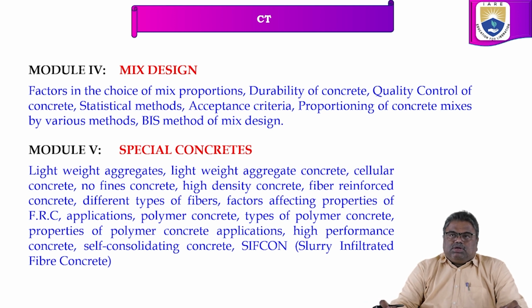Concrete is very strong in compression and very weak in tension. So if you want to improve the tensile properties of the concrete, we have to introduce fibers into the concrete. Those fibers can be steel fibers or plastic fibers.